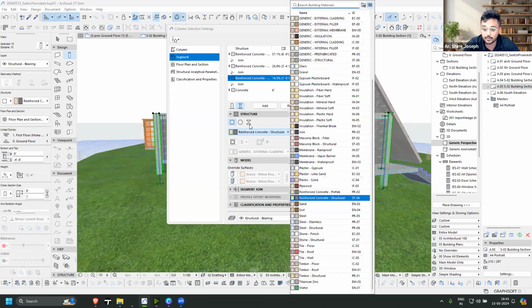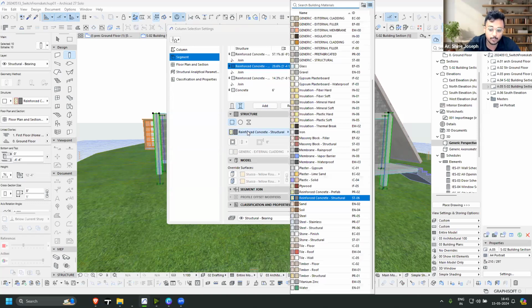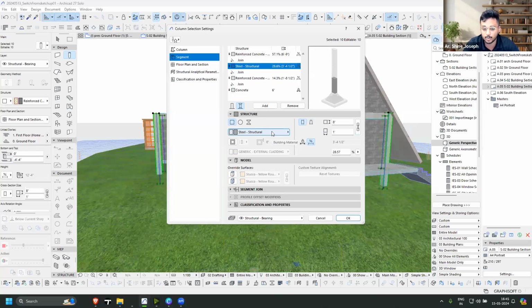For this element I'm going for a reinforced concrete structure itself, and the next element, which is on the top, I'm deciding that I need to have some kind of a metal plate around it, just to showcase it here. The only thing is we change the material. Probably we'll take structural steel, any type of material that is most appropriate for this case. We'll maintain the dimension. The only thing is we are going to fix the height to be probably 1 inch.